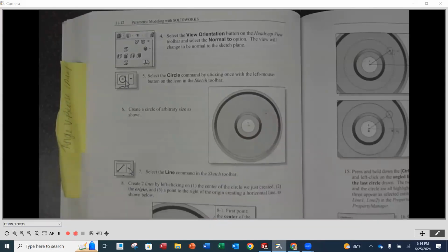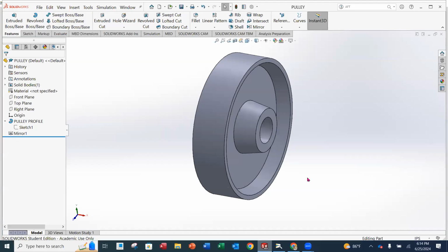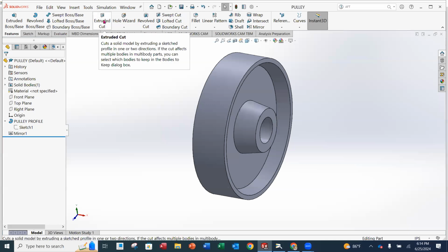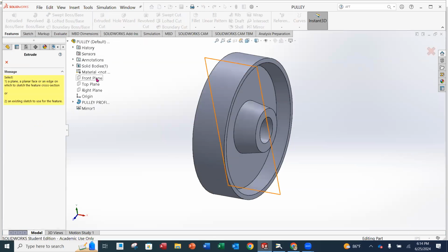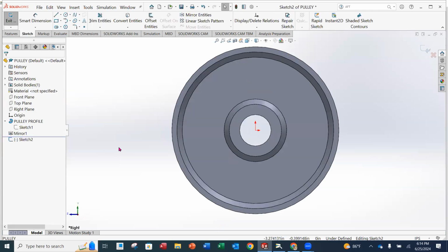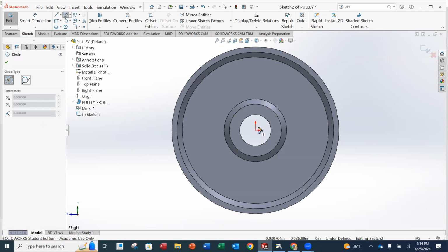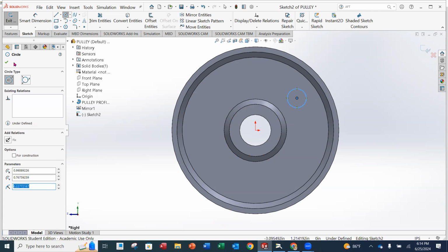Okay. So we are going to, back to SolidWorks here, do an extrude cut. And we are going to go on that right plane. I want to draw on that plane right through the middle. Okay, on the right plane. And I'm going to sketch then my hole. And from the origin, it's going to be up and to the right in this flat area, right about there.